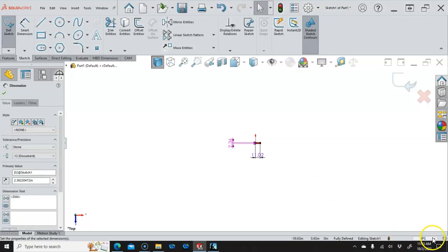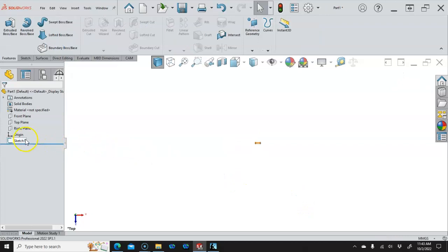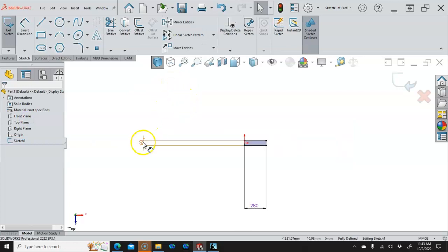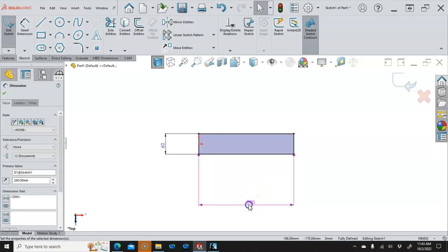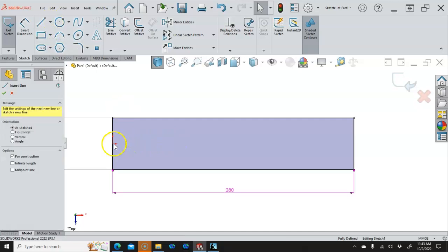Okay, so now when I go into the millimeters, grams, and seconds, I know it's going to kick me out of the sketch. We can right click, edit sketch. It will zoom up for me. Dimensions are out a little ways, not too bad. Sometimes they get thrown pretty far. And then most of the time I'd do a center line, infinite length.